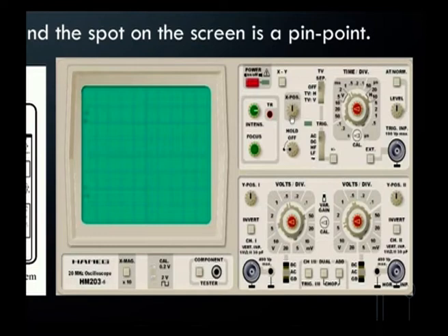We need to move the signal along the x direction, that is the x axis, the horizontal position. That horizontal control can be done with the help of this knob, the x position. By changing this, we can achieve the horizontal movement, and by changing the y position, we can move the signal up and down. That vertical position can be achieved with the help of the y position, and this has two knobs. We can control the vertical control system with these two knobs.